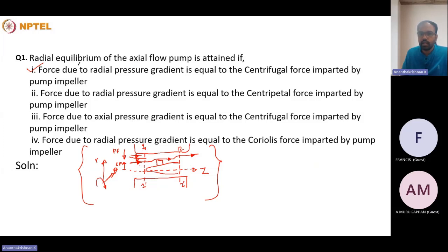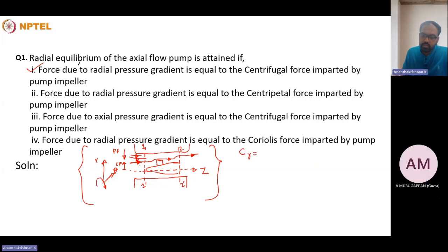Instead, they would not be a straight line, but rather inclined a bit, in a more staggered position, as you had seen in this control volume. Since it is not the case, we can assume that the radial velocity component in the case of radial equilibrium is equal to 0.